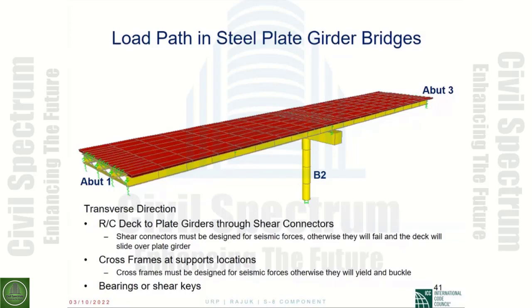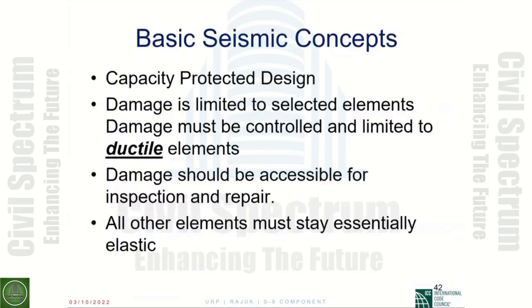You want to make sure to design them for the seismic forces, if you want to have them stay inside the elastic range, or as you will see later on, you could allow them to yield and to buckle so that they will be able to dissipate the seismic forces. Bearings and shear keys will become extremely important. So these are basic concepts.